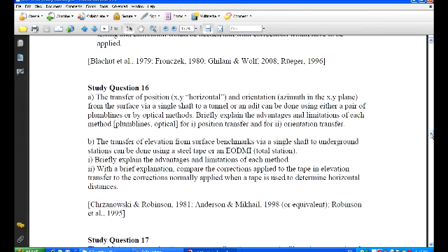So plumbing up would be a zenith plummet, plumbing down would be a nadir plummet. It's a little different than the optical plummets that you use in the tribrach because there's a much higher precision to the definition of the vertical through the level vial or automatic mechanism, and then the focus is much more sophisticated. It's basically a telescope that's looking through a prism either straight up or straight down.